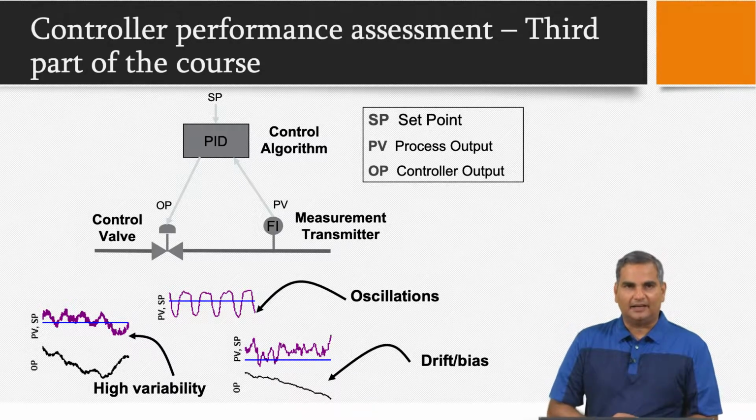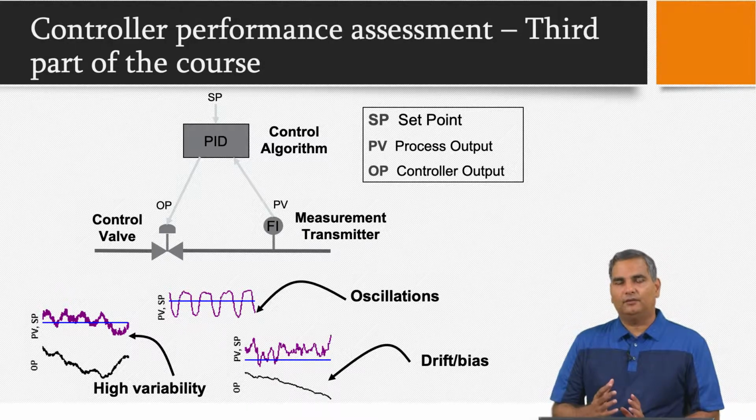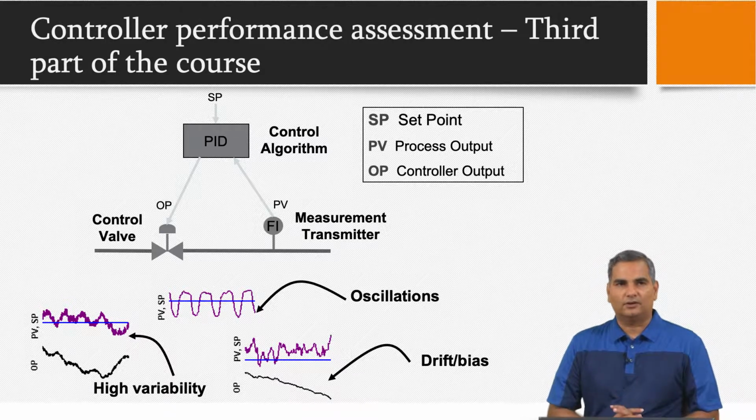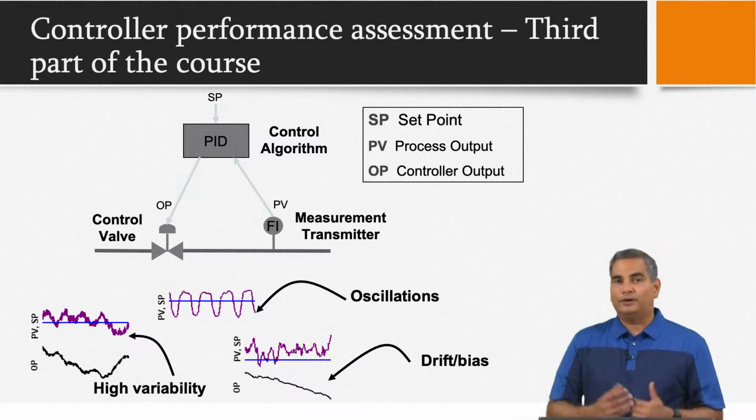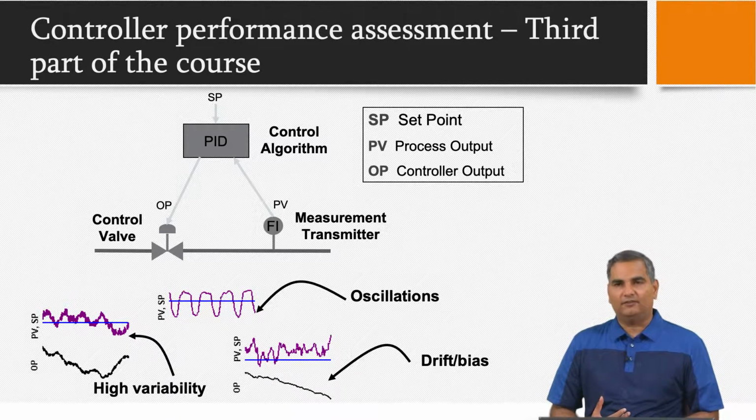However, just as a recap of what I said in the introduction, basically we have learned how to come up with control structures, how to tune these controllers and so on. However, once these controllers are in place, they work for a long time. So, once they start working, the questions of interest are, if I have several controllers in my plant and I have, let us say, a budget to maintain these controllers, which ones do I maintain is an interesting question to answer. So, that would mean answering questions like which of the controllers are not doing as well as they are supposed to do.